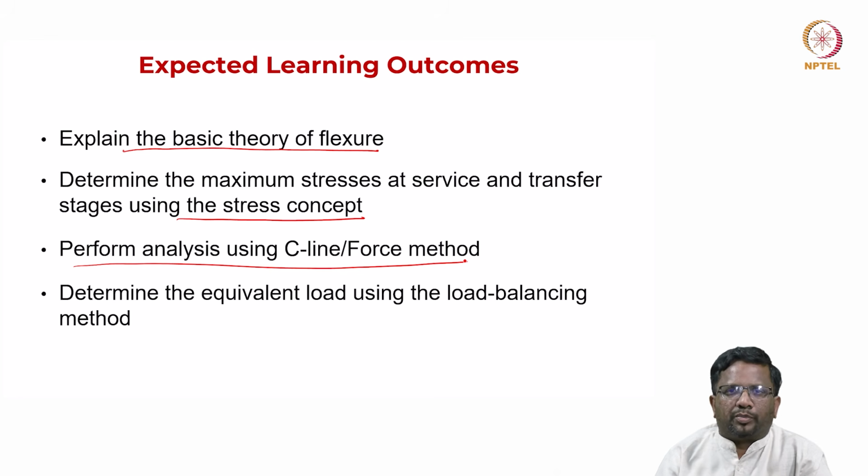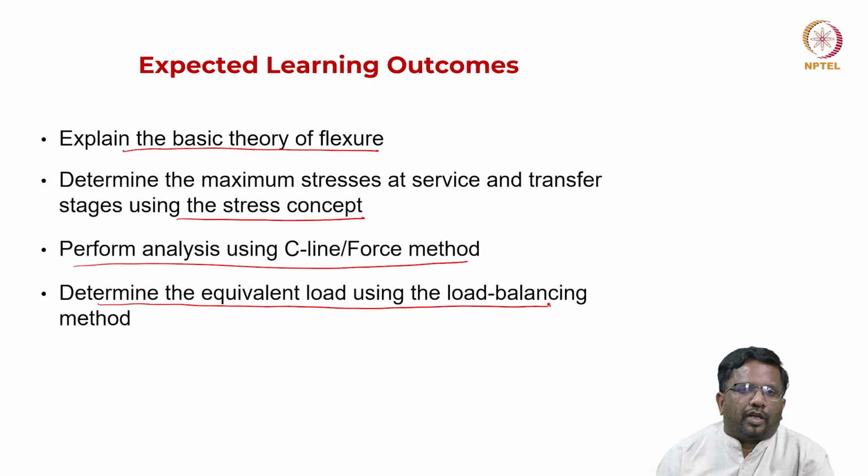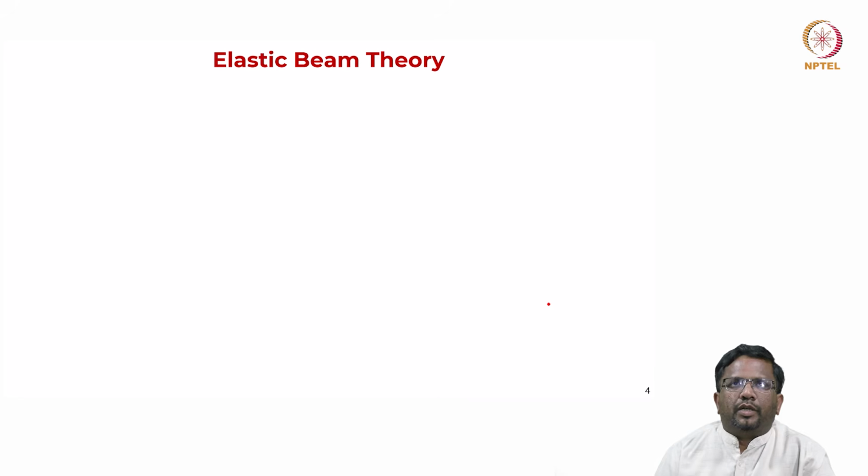The student should be able to explain what a force method is and how the force method can be used to calculate the stresses, and then the equivalent load method for calculating the load balancing. So we call that the load balancing method. The student first needs to calculate the equivalent loads, and then using the equivalent loads we can do the analysis.